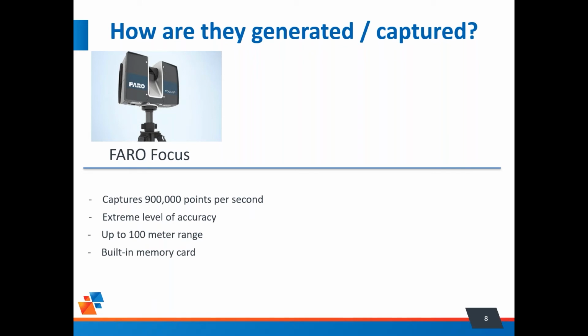It has a built-in memory card. This is also a fundamental way that the Faro Focus works. It has a built-in memory card where it stores each individual scan. And it could take minutes per scan. It could take 15, could be 20, could be 30 minutes, but you can adjust it if you only need a certain amount of data, or if it's a small room, you can get it right down to say 2 minutes if you don't need color and you just need a quick scan of the area.